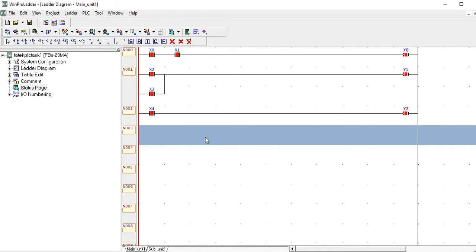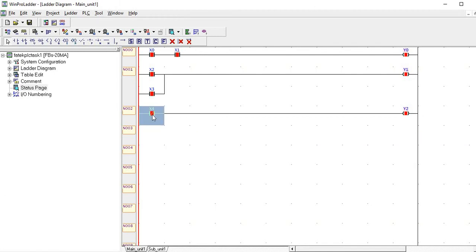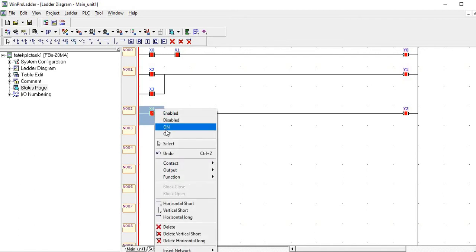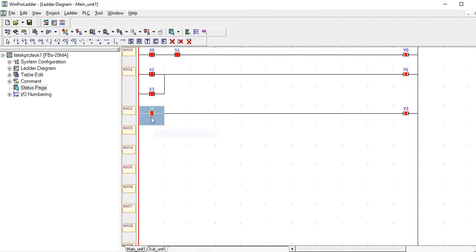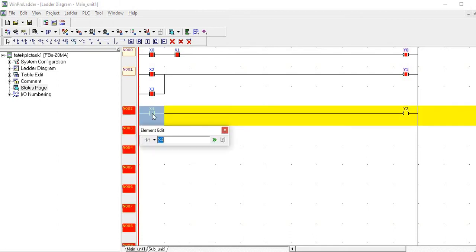Off. Look, it is a normally closed switch. Normally closed means, look, right now this switch is off. When we turn on the switch, when we give power to this switch, the normally closed switch suddenly opens its contacts and becomes an open switch.